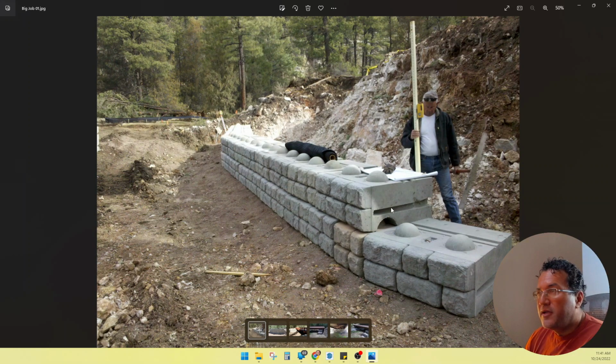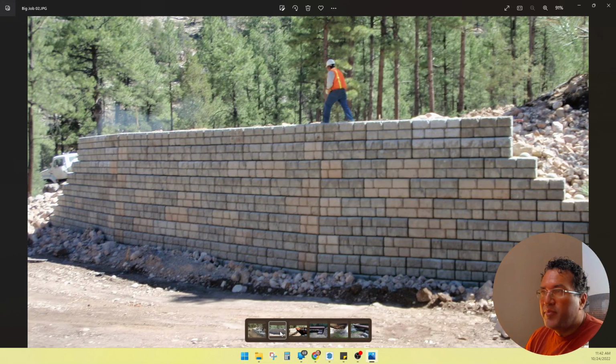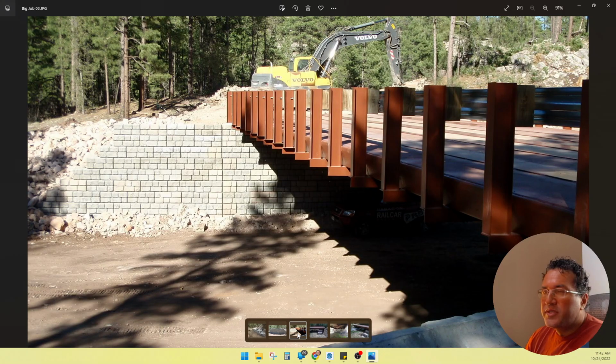Here's another great picture of the blocks. You can see that they're just 1 ton blocks. They have lifting hooks on the very top. They're just like Lego blocks. They just kind of interlock. So with these blocks, we can do some pretty tall abutments. You can see there's actually another row underneath this. That's 1, 2, 3, 4, 5, 6, 7, 8, that's 9 courses there. This is what the bridge looks like when it's done.